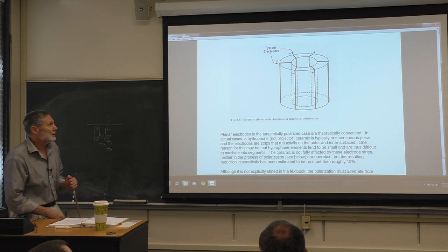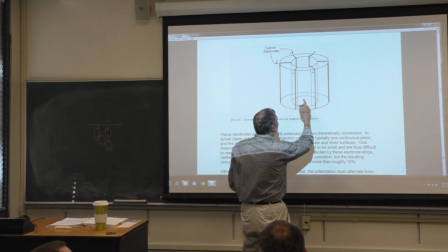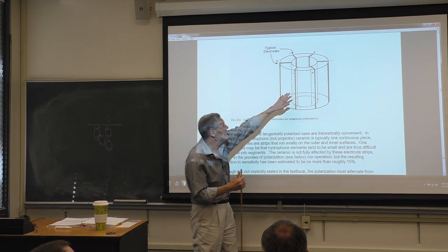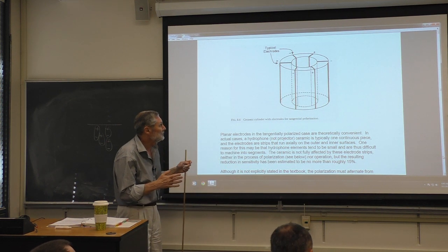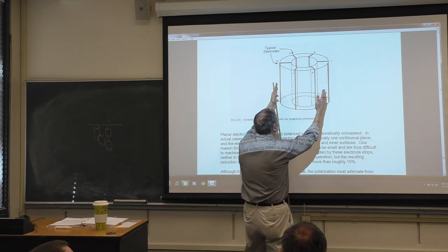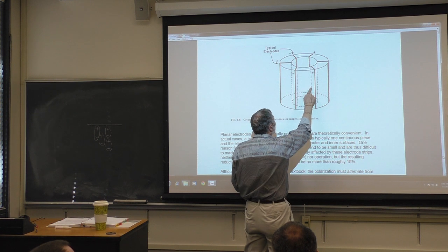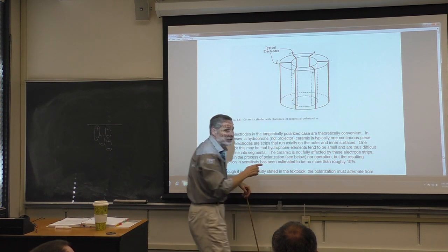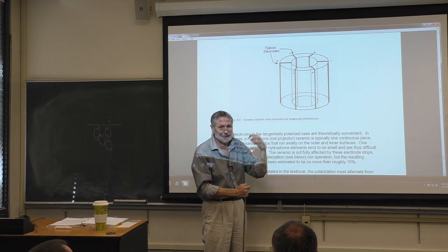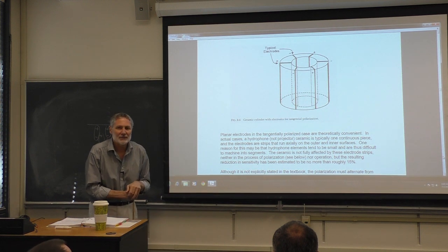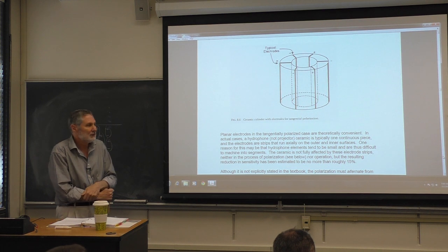So you end up with segmented material here that's polarized in the opposite direction. It alternates just as the electric field alternates. And you need that, right? Because when a sound wave comes in and you get a compression here and you get a change in voltage, you want the change in voltage here to add with the change in voltage here. And if you don't alternate those polarizations, they're going to cancel. They probably won't cancel exactly, just due to the non-uniformities, but approximately they're going to cancel. So you've got to alternate them.